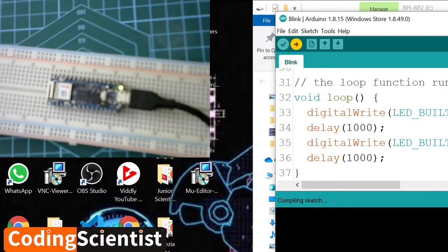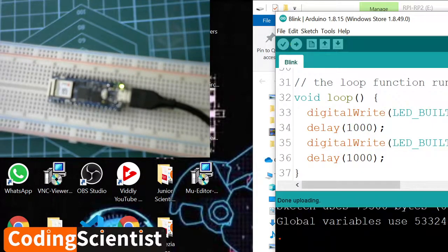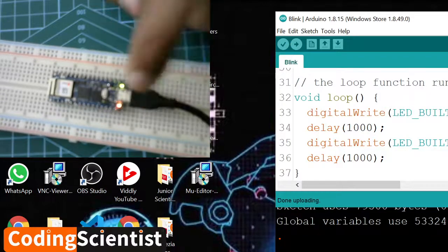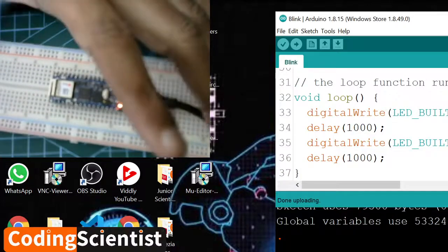Compiling sketch. Uploading. It's done uploading and I can see the blink is working. So there is no problem with the board.